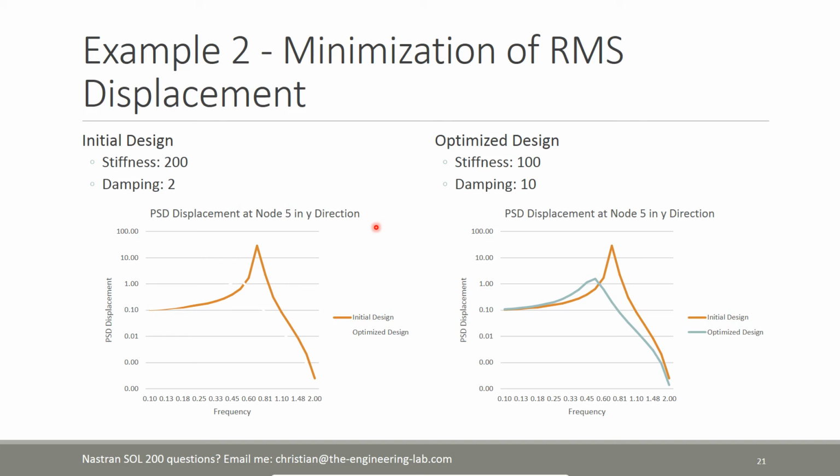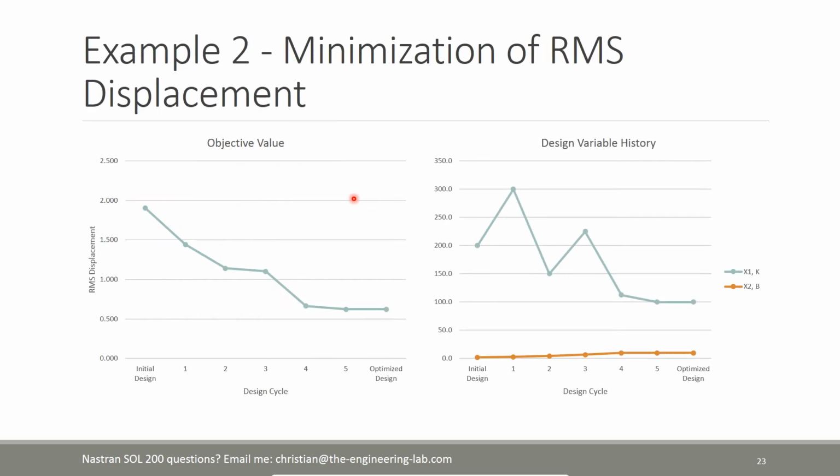The biggest thing from this tutorial I wanted to show you was, one, how to use the web app to create your design variables, your objective, and your constraints. And number two, how to validate that you've properly configured your variables, your objective, and your constraints. The validation is very important when you launch a full-blown optimization of, say, a big vehicle or a substructure. You want to make sure you've done everything properly up front before you commit possibly days' worth of optimization with your high performance computing hardware. So with that, let's go ahead and start concluding this presentation.